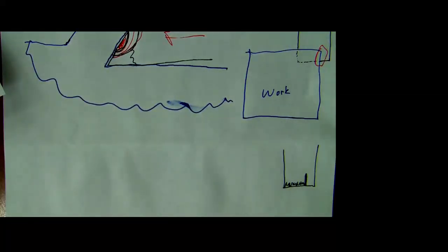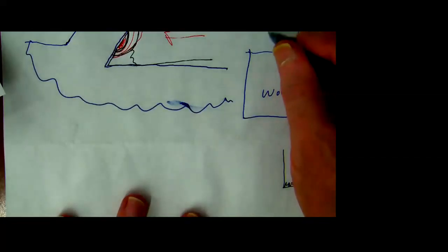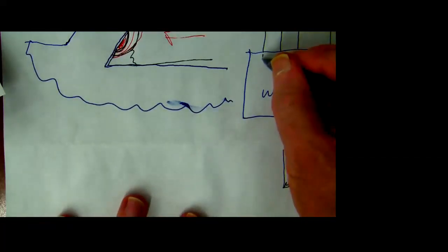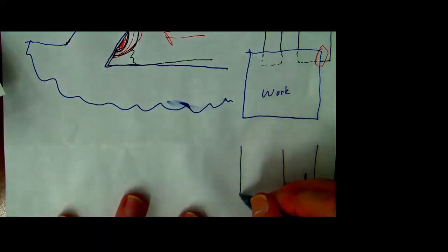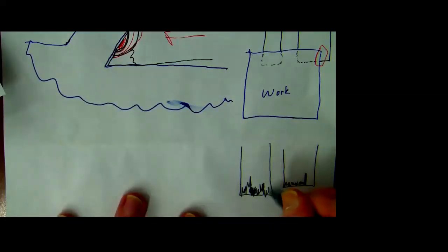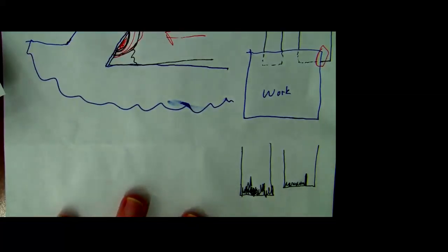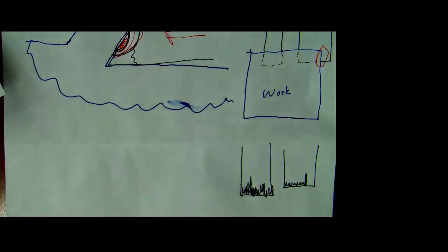And in reality, this is a problem even if I'm cutting down the middle. If I'm cutting this one, you know, life's not fair. If I'm cutting that one, I'll probably get a wear that looks like that. Okay, what's the flank width wear of that? Well, you know, draw a line somewhere to the middle and call it what it is, okay?